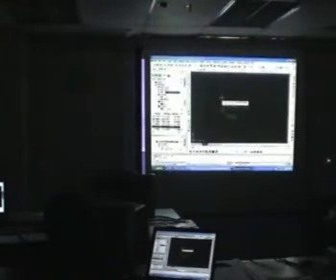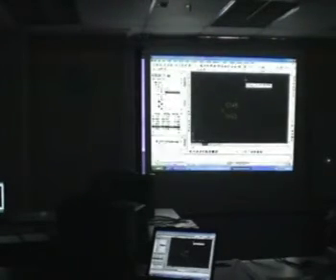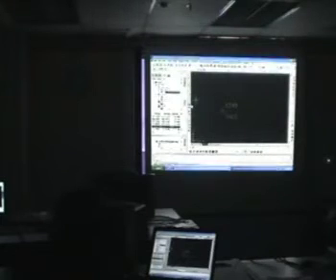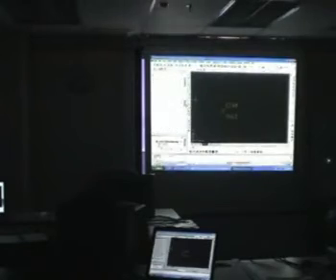Now the bit about contours and the triangles that we want to generate from the surface, it's very much different from Land Desktop in the sense that you don't have to create it. When you generate contours there, you go to Terrain, Create Contours, select the attributes, and what your interval is and all that. We don't have to do that in here. What we need to do is set the settings in Civil 3D. We still need to specify what the intervals are for our contours, and maybe what the colors are for your contours. But that falls under settings, surface styles. We've got quite a number here actually, but borders and contours.